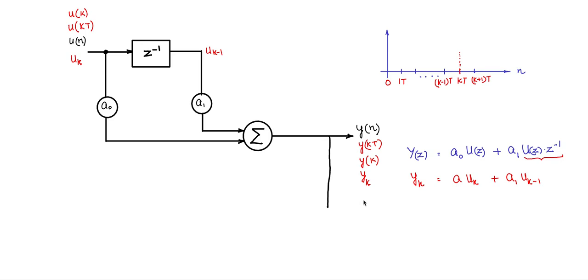Let me now include the feedback part, the IIR filter. So I am going to feed back y through a unit delay and a scaling factor. This is z to the power of minus 1. So this is moving in this fashion. The signal B1. So this is the feedback part. I am just only looking at first order so that it is much easier. Now write the equation for y k.